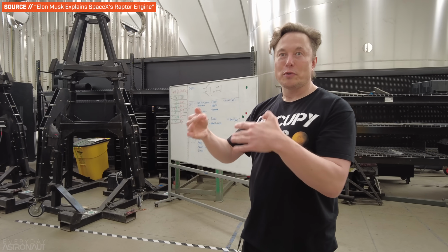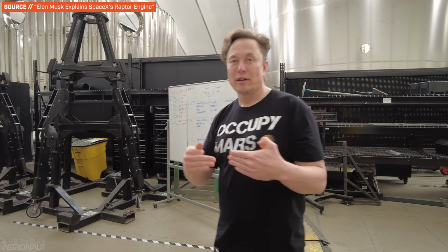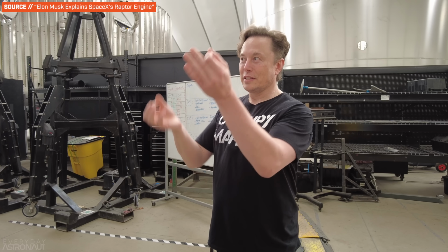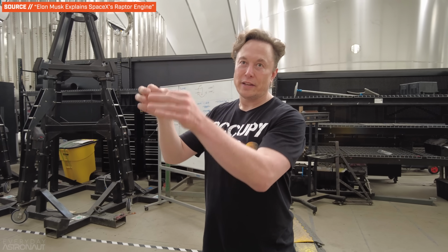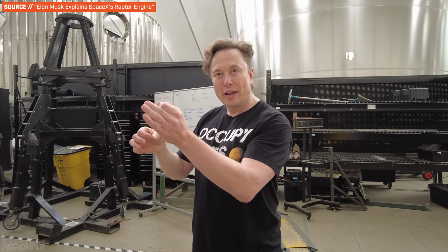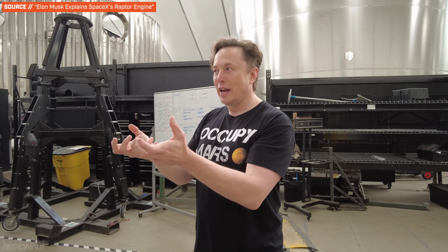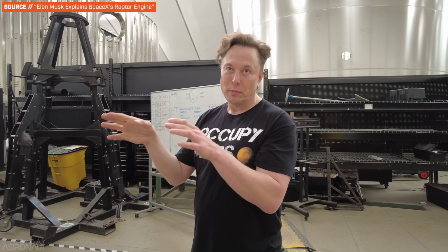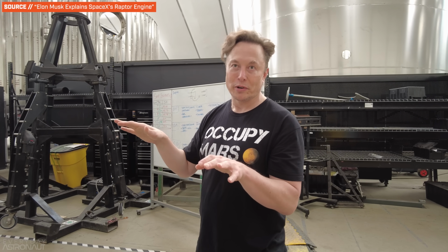Yeah. So the start sequence for Raptor is insanely complicated compared to the start sequence for Merlin. It has to be perfectly precise. You're doing this delicate dance between the fuel power head and the oxygen power head. And if they get out of sync, then you can go stoichiometric in the preburners and melt or explode the preburners. This means managing the timing of valves, startup, and even throttling is extremely hard to master and requires some very deep pockets to perfect, which is why we haven't seen that many full flow engines developed.